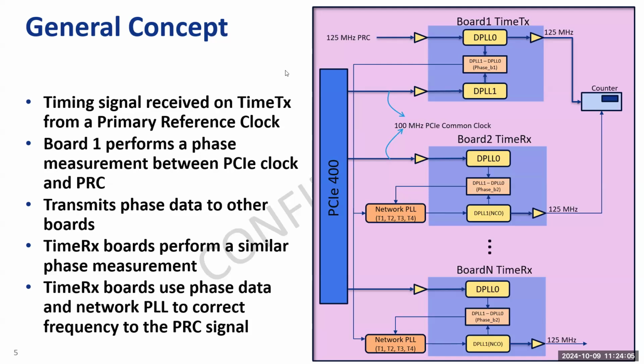But of course, it was commonly done years ago in telecom, right? It was plesiochronous type clocking. But the challenge with data centers and with the PCIe common clock is the whole spread spectrum clock. Even if you add some sort of filtering to try to filter out the spread, the alignment of the edges you're trying to measure, you can't guarantee they are equivalent on two different boards. Yes, so that's one challenge that still has to be overcome with this type of implementation. So you have to find a way to do that.